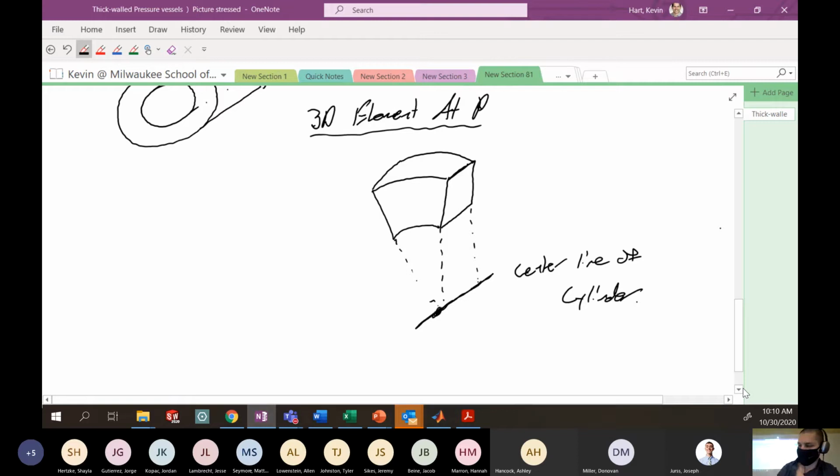And we have no shear stress, but we're going to assume that we have some of the other types of stress. So the other types of stress you might see, we wanted to dash this in here. Okay, it's the best I could do. So this would be your radial stress that develops, sigma r. You're going to have some hoop stress that develops on the sides here. This is sigma theta.